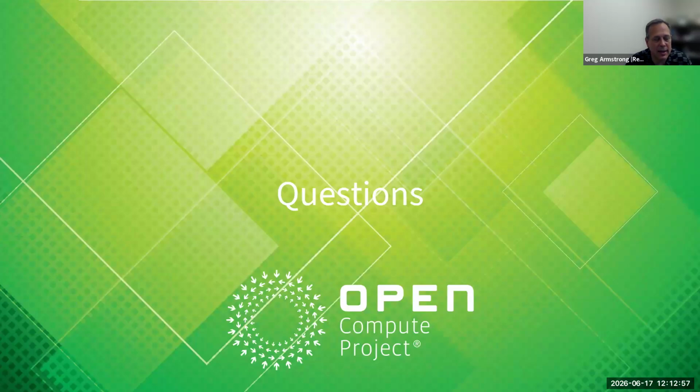But if you want to start saying, well, what if I want redundancies and resiliencies and stuff like that, and maybe some server cards will do better calibration out of some of those delays, right? They might say, hey, I will guarantee the max propagation delay of that clock signal will be X going to your connector, right? And then the card plugged in can then say, well, from the connector to the CPU, GPU, I can manage that as well, right?